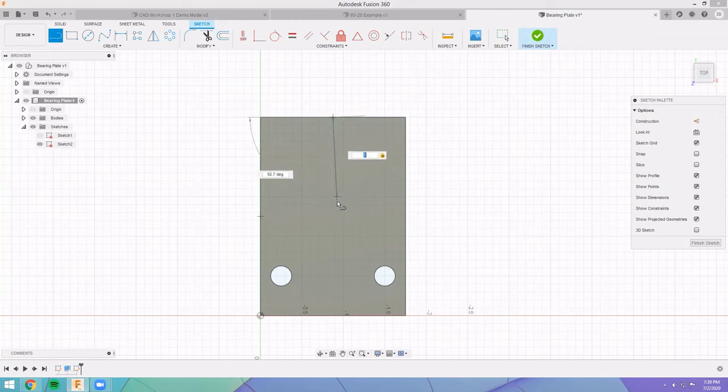Most of the time, you're going to be working in 90 degrees. If you'll notice, it's a little harder to see, but right here, you actually get that same perpendicular constraint, that same 90-degree thing. This is the same as what we saw when we brought this all the way down to the bottom for the mirror. That's good. That means that this thing is going to be snapped to 90 degrees, so no matter what we do to it later, it's going to stay straight up and down. So we'll just click, that's okay. So here's all our constraints, perpendicular, midpoint.